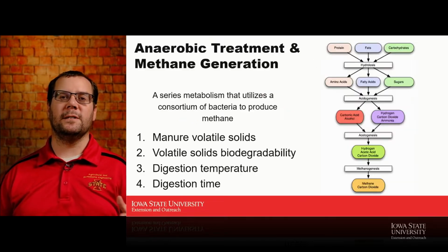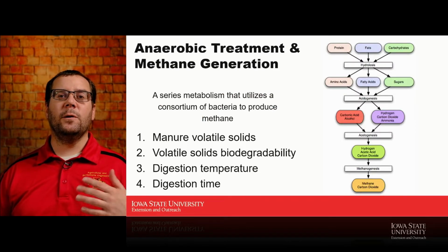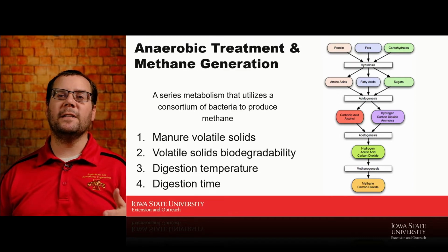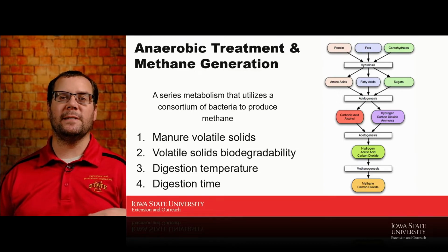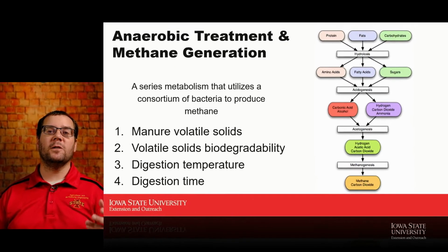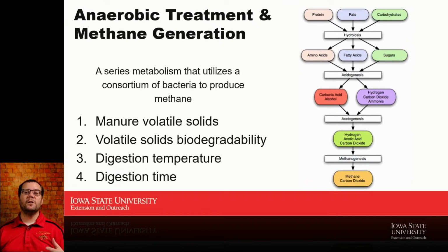The anaerobic digestion and treatment process, I have it diagrammed here on the right, and it's really a flow from the stuff we start with. And those things probably look pretty familiar to you if you think about human diets, right? It's carbohydrates, fats, and proteins. And the microbiology of our treatment system is going to take those, break them down, and turn them into various process chemicals along the way. Free fatty acids, and then finally down into short-chain fatty acids.